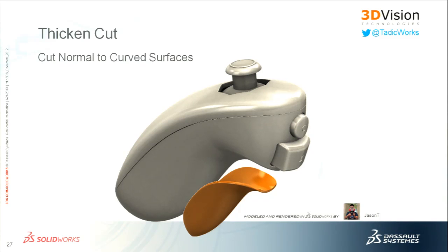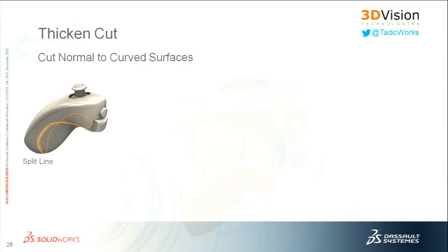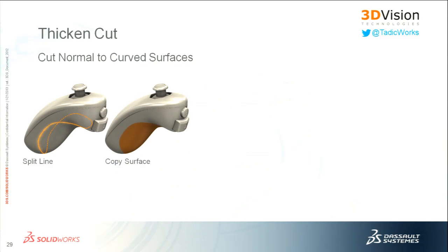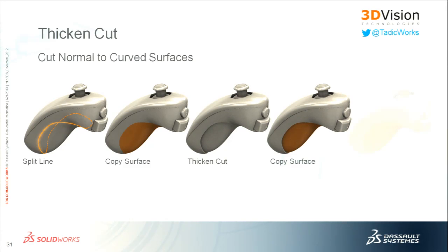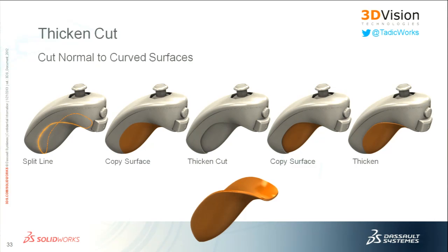The workaround for that is to create our own surface, a separate surface body, and then knit those together. And we could do that in a bunch of different ways. We could sweep a surface along an edge and draw the profile of it and make that profile tangent to the previous body, or with a spline if there is curvature and have continuous curvature between those two, but we could talk more about it afterwards as well. So here's that process once again. If you come back to this and download it, that's just it explained.